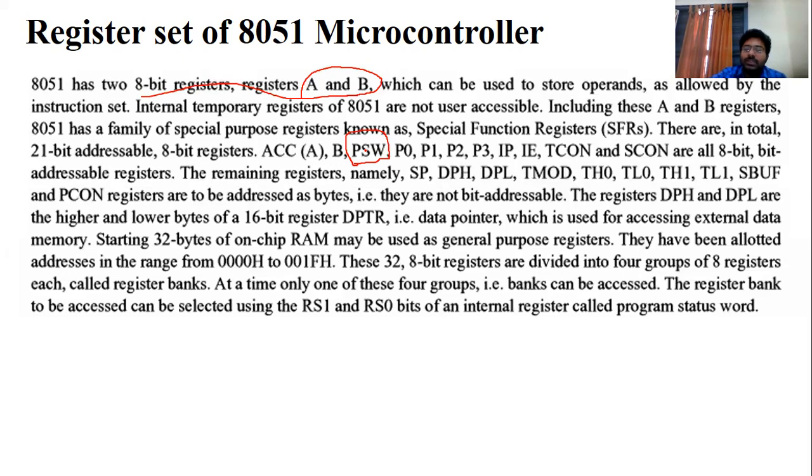How is the status word changing its bits? You know that a flag is one bit, either set or reset, that is, one or zero. How are these flags set and reset? Looking at the CPU, the arithmetic and logical unit is directly connected to the PSW to change its bits.